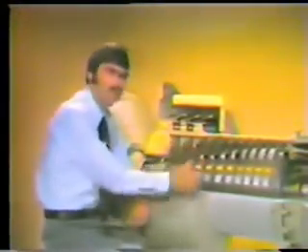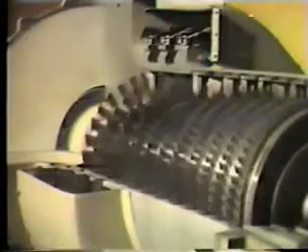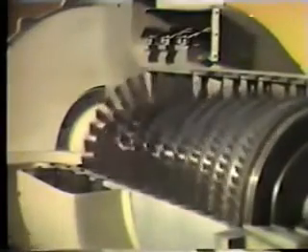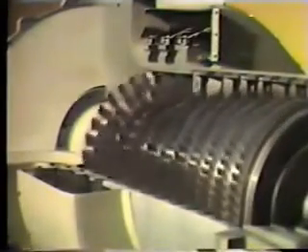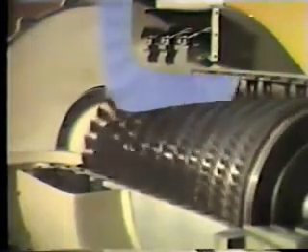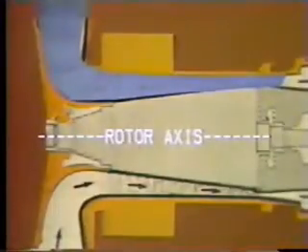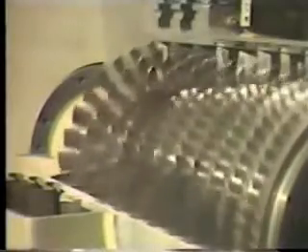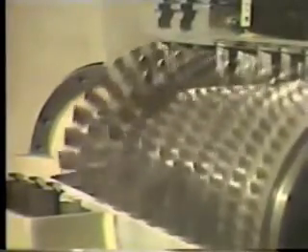The principles of compression are best understood by first looking at the construction of the compressor. The flow path is formed by an annular passage around the rotor assembly. As the air flows along the length of the compressor, the air path decreases in size. Since the path for the air is parallel to the rotor axis, the compressor is an axial flow type. The work of compression is done by several rows of blades, similar to the blades of an electric fan.